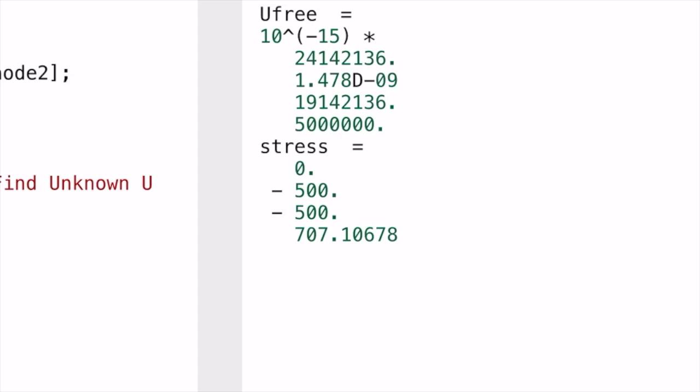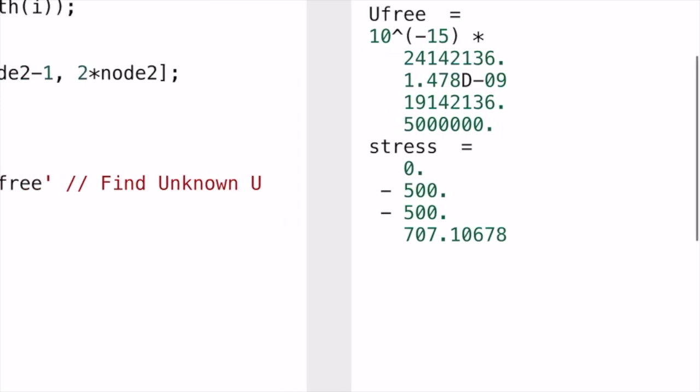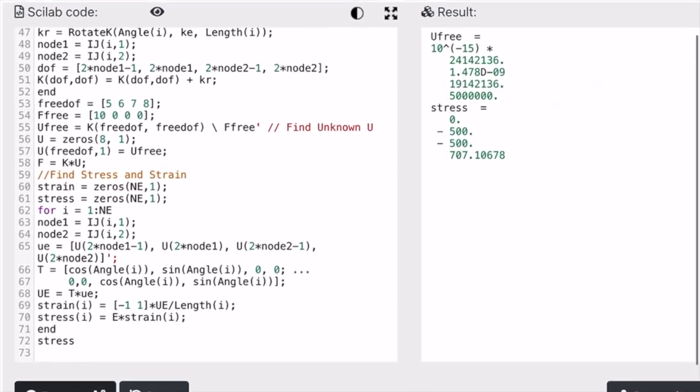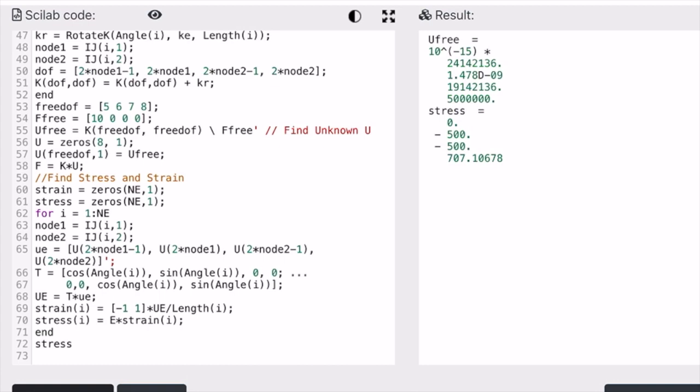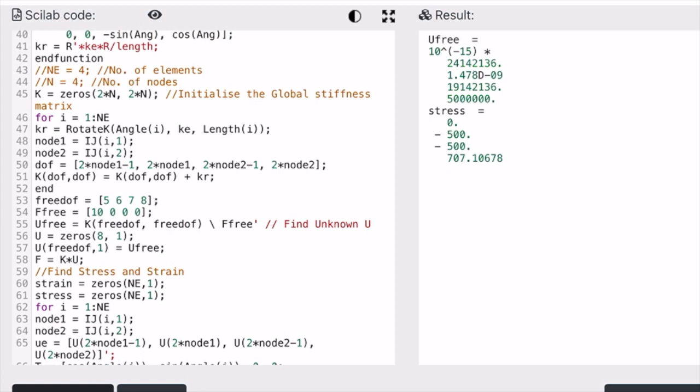So I think the way we numbered it, so one is vertical, so its second is horizontal, so it should have tension rather than compression. Then we have fourth one diagonal. So just looking at it, look, it should be in compression. Fourth one should be, fourth is diagonal one should be compression. So it looks like we are getting the sign, somehow we are not getting the actual sign. So what is the problem then? So let me see. So u1 u2 minus u1. Okay, so we have to see angle and all, whether it's correct or not.